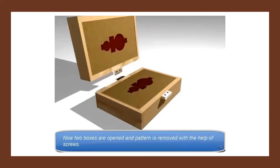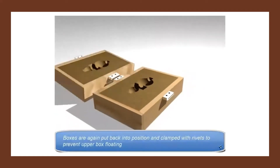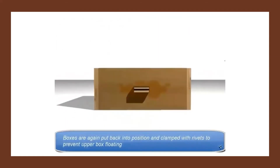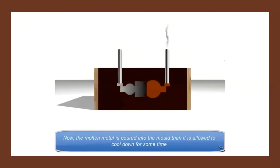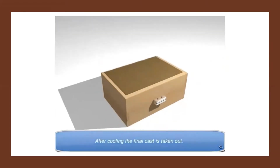Now two boxes are opened and pattern is removed with the help of screws. Boxes are again put back into position and clamped with rivets to prevent upper box floating. Gates and sprues are formed to pour the metal. Now the molten metal is poured into the mold. Then it is allowed to cool down for some time. After cooling, the final cast is taken out.